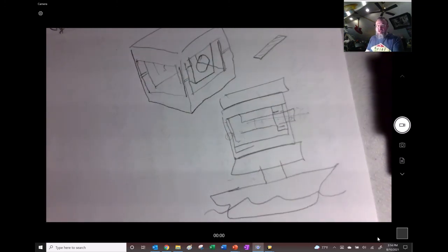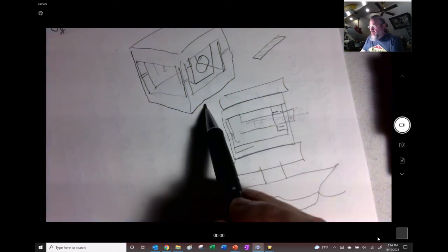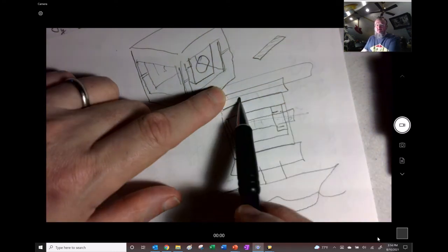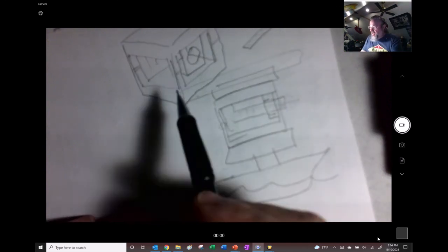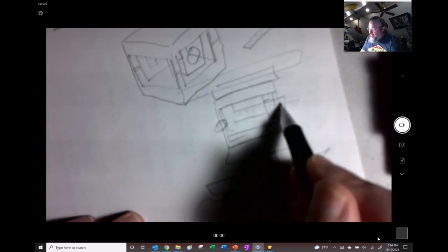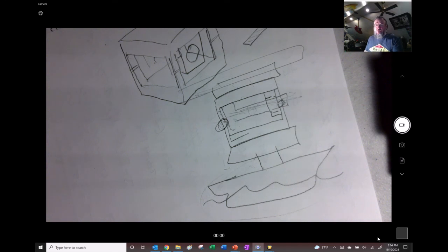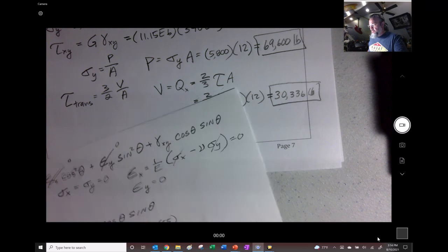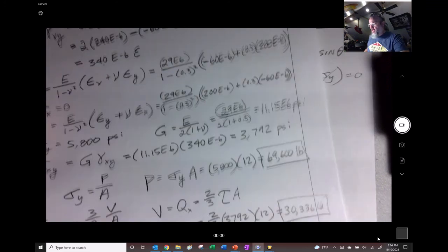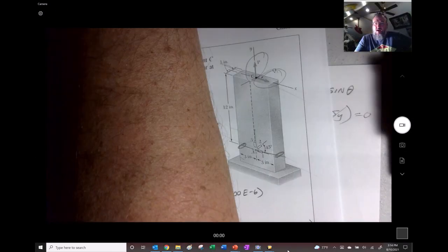That's in the towing tank. Of course, this thing is much bigger. This is just a little component that's inside there, but this would be the thing that's moving the boat along. So the resistance of the water would be measured by how these little posts bent and the distance that they would be able to measure through there. They were able to calibrate this, and that would be called a force block. I wonder if I did a Google search on force block, I'd be able to get some results that would describe that. But it's another way of measuring force.